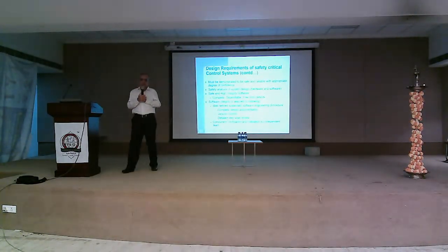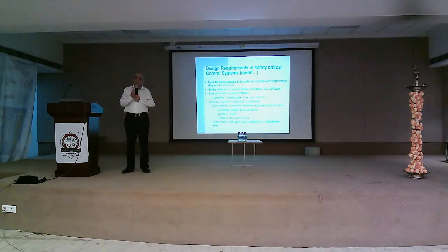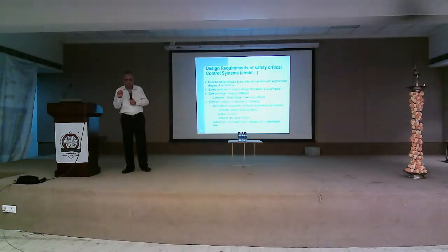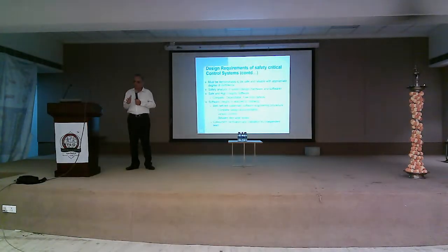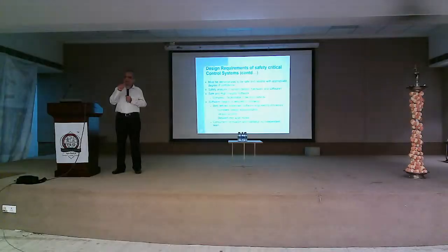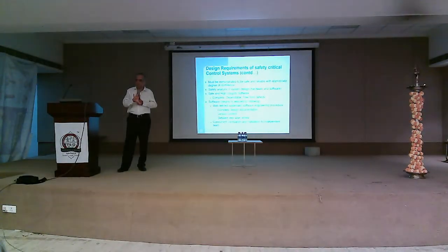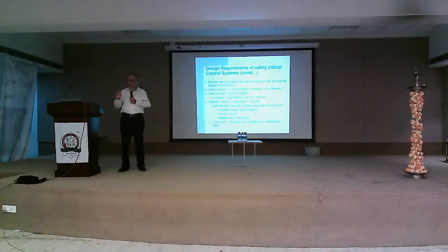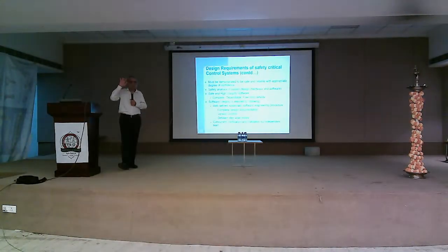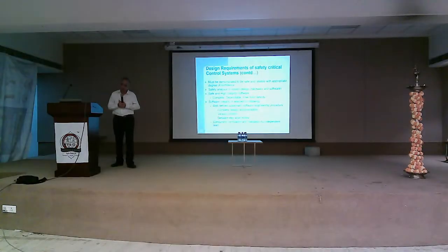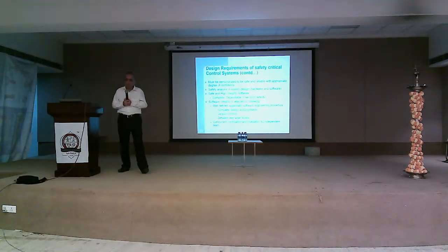So we have hardware and there are n number of components in that. Any single component failure is taken as a failure of the card. We find out the failure rate of all and calculate the reliability of that. And since they are triplicated boards and all other boards, we make a fault tree and find out the overall system reliability. It can be done.